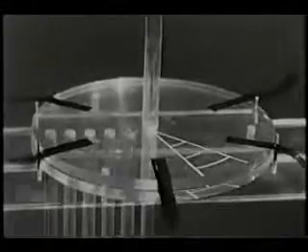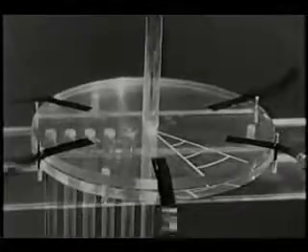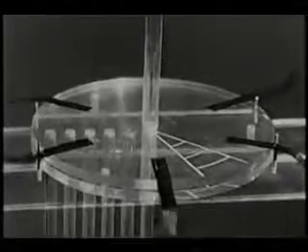But in this particular experiment, the mass acceleration forces are generally larger than the viscous forces, and so they govern the shape of the pressure distribution. The subatmospheric pressure over most of the area explains why the disk is lifted.